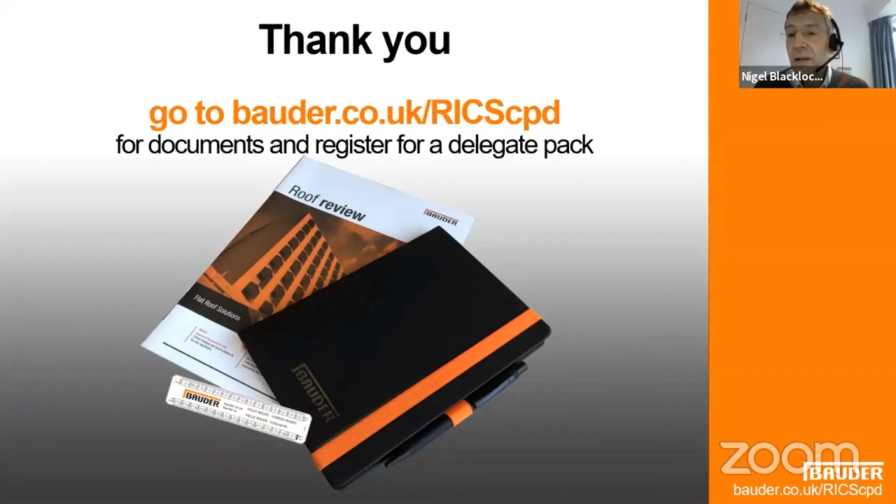So it tends to be timber decks that the insurance industry will look at more closely, and then they will tend to look more closely at what the insulation type might be. But hopefully what I was also demonstrating there is that even combustible insulants meet the current standards for the building regulations. Now, an insurer would say, yes, but we're concerned about buildings as well as lives. But many of them will accept combustible insulations as long as it achieves B-Roof T4. It mainly tends to be, if it's a timber deck, that they would probably then insist that the insulation was also non-combustible.